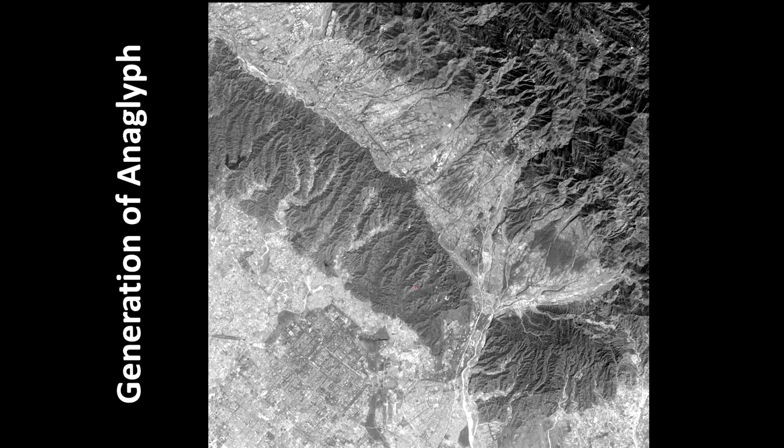This is a 2D image, and you need to have two images of the same area. This is a typical, robust methodology which we use in photogrammetry. The 2 photographs have been taken. For example, if you have a flight here, and then you have 2 cameras facing like this, and you are recording the data on the terrain, you have the forward and the after.